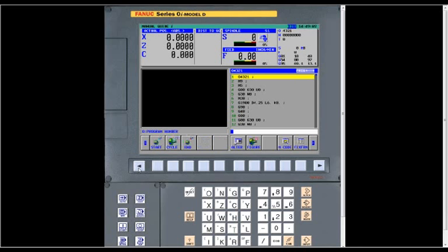When you're doing a turning cycle with a hollow cylinder, say you're boring out the inside of it, the last move that you would make would go down to the smallest size of that hollow cylinder, and then the control would know that that was where the stock would be removed. So it's very simple to do. It's just based on the geometry that you described for that hollow cylinder within the turning cycle. That's how you do that.